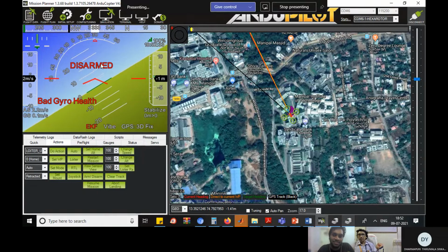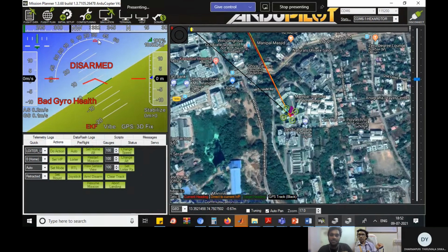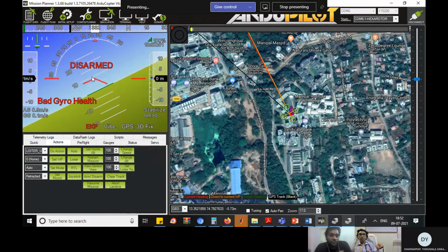So this is actually a right turn, okay? And what this angle suggests, this means 30 degrees. Now this is a 30 degree angle. Right 30 degrees. And with the pitch also. Pitch now is nearby some 10 degrees. Yes, sir. Okay, you can check 10 degrees matching. So what is this line matching with? This is the horizontal line of the aircraft, and this will tell you your altitude, this side airspeed, vertical speed. If you're going like this, then you will see the speeds.